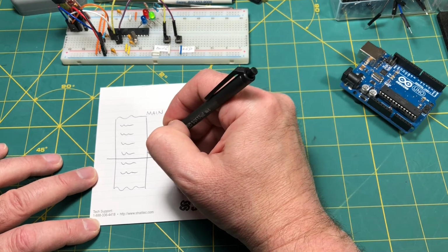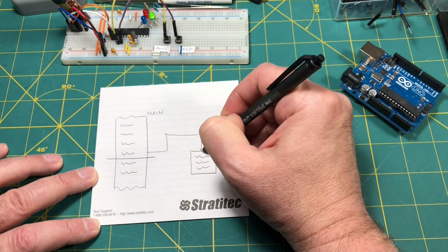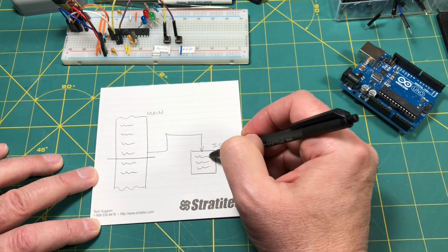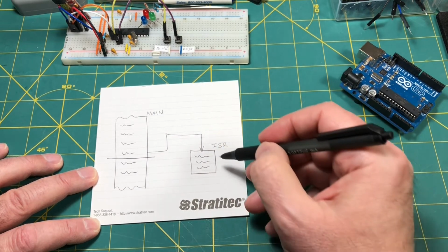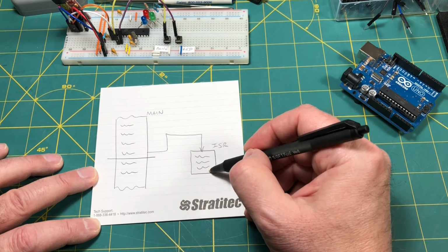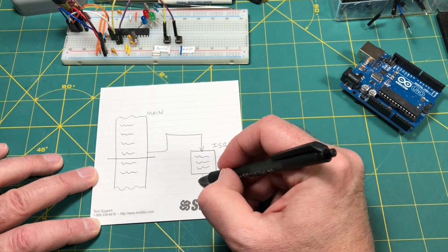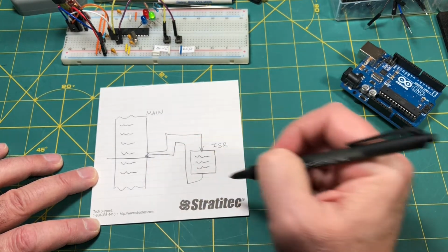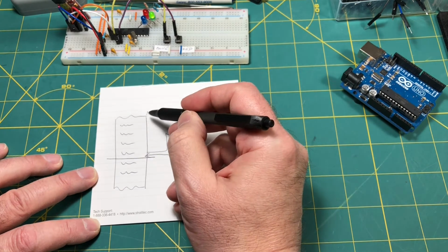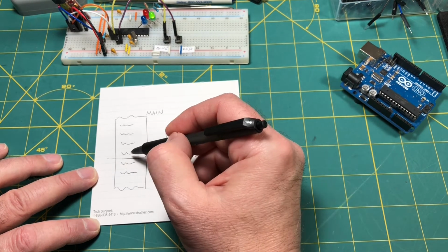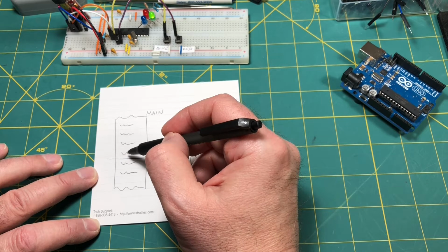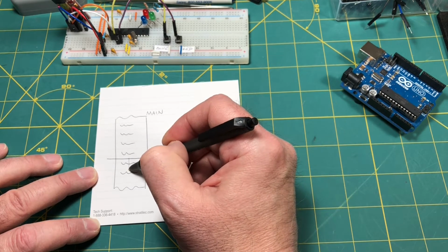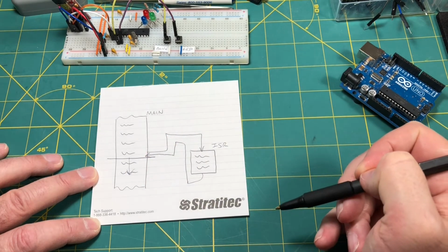It will leave and go to the interrupt service routine, which is the code that we want to handle our interrupt with. So the interrupt service routine instructions are executed, and then at the end we will return exactly where we left off, and the processor will reload hardware flags, program counter, whatever else it needs to reload, and will continue on with what it was doing as if nothing happened.